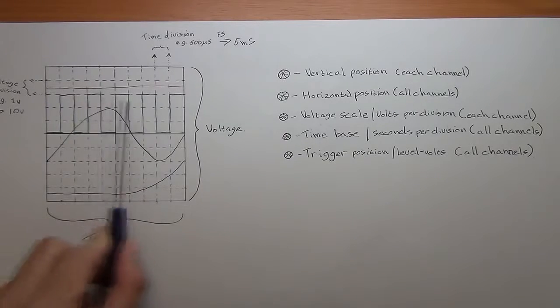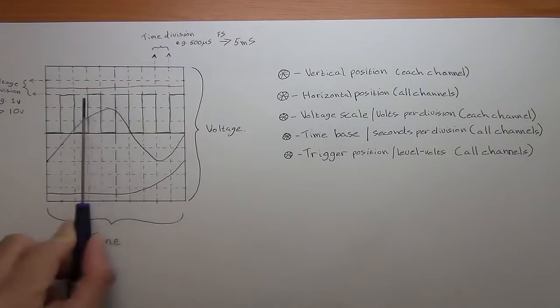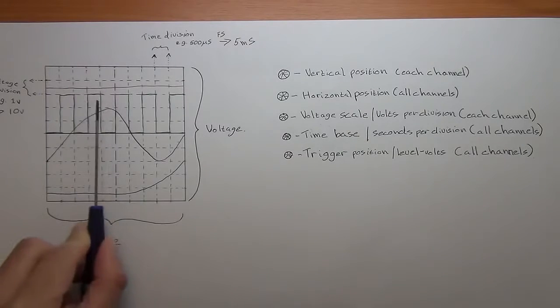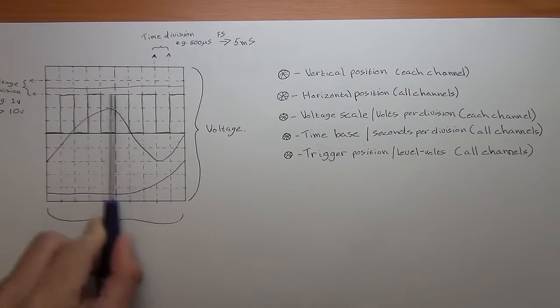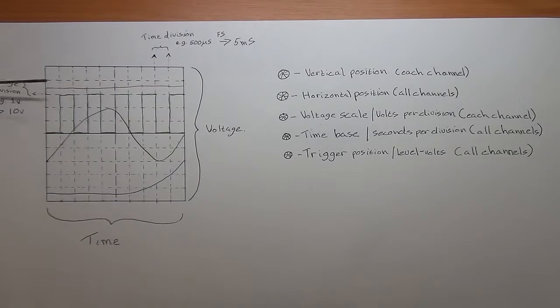And that can be rather difficult to evaluate if you want to keep it live, if it's jutting around and moving around. So what your trigger does is you set a level at which you want your scope to capture that signal. And it's adjusted down on your voltage division. You move your trigger down to the middle point of your signal.